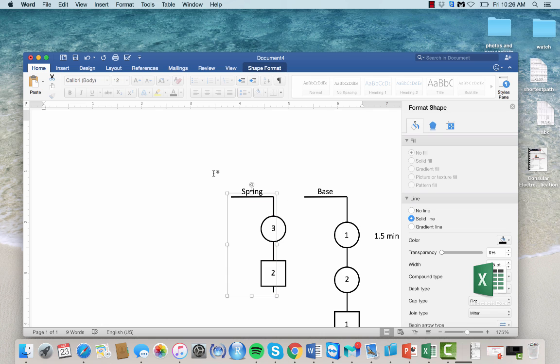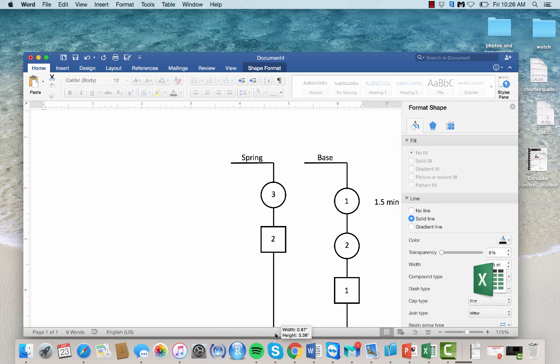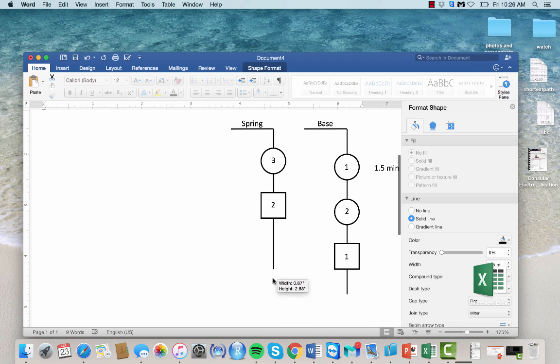The frame means that it's a grouped object, and we know that this horizontal line and this vertical line are grouped. So in order to just lengthen the vertical line, I once more click on the vertical line, so you can see the small squares here, which means the vertical line has been chosen, and I extend it to here, let's say.